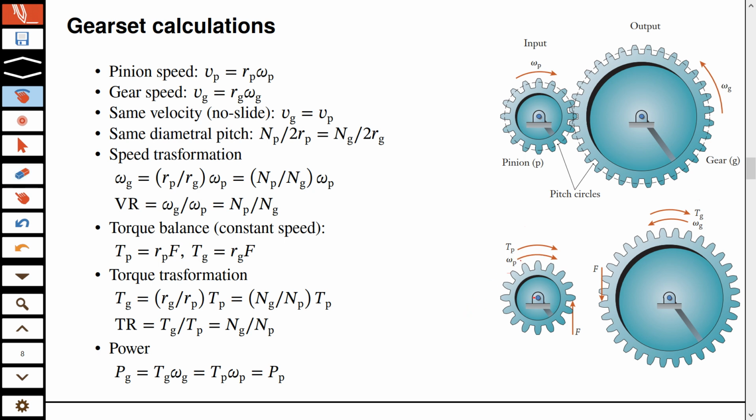Okay, because it's a free body diagram, the force associated with this torque must be balanced by some other torque. Actually, because it's rotation, you need a torque balance. Now we also need to introduce Newton's third law, because these are two bodies and these bodies interact. You know from Newton's third law that whenever two bodies interact, they will introduce a pair of forces.